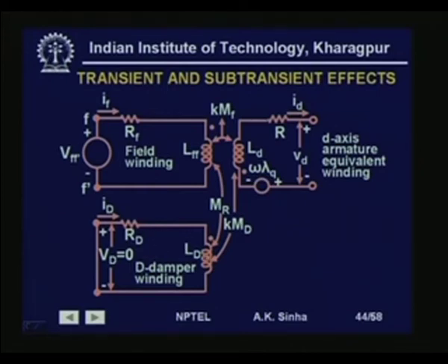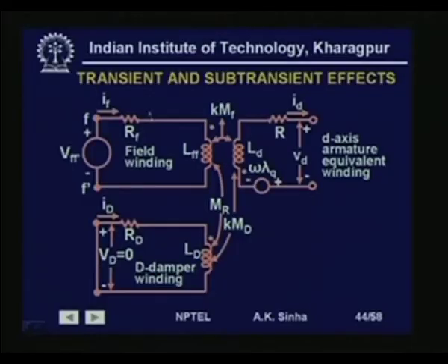There is no current flowing through this, and these two circuits are only valid, and then the field time constant is somewhat larger. So, that again dies out with some time, and then finally, we have only the synchronous impedance of the circuit remaining, and therefore, we define three different reactances or impedances for this circuit.